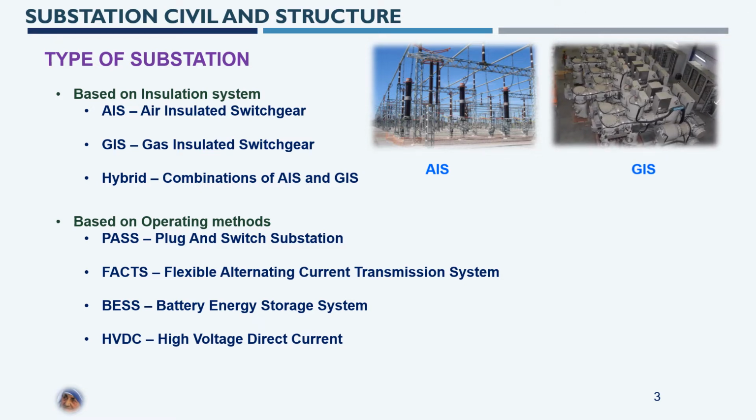The next picture on the right side is a gas insulated switchgear type of insulation system, where the three conductors for a three phase shall be transmitted through a closed conduit which is filled with a gas called SF6, sulfur hexafluoride. This gas is utilized as an insulation material among the three closed circuit conductors. Generally GIS equipment is costlier when compared to AIS equipment, whereas on the other hand AIS requires a large space of land. It also includes some large scope of stormwater drain and metal spreading, which are other civil scope. In case of GIS, special care is to be considered while designing a GIS hall, which is a major building having a higher height compared to AIS buildings.